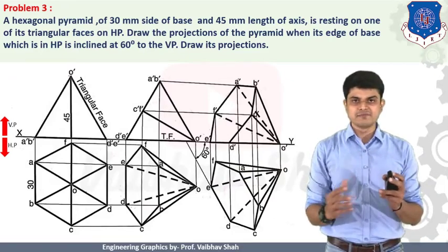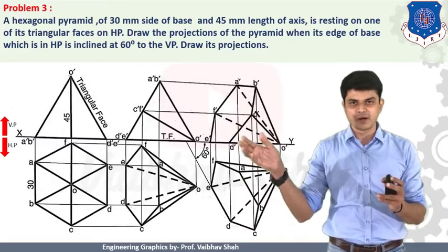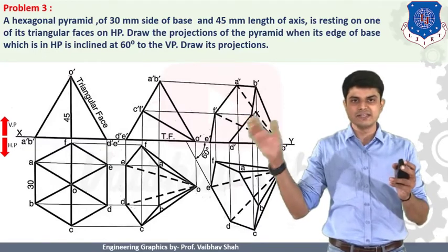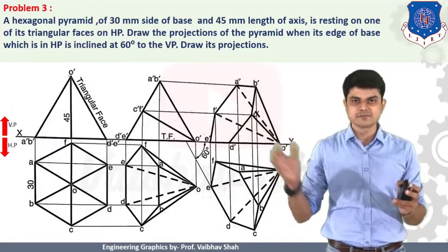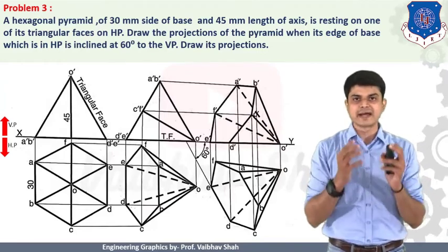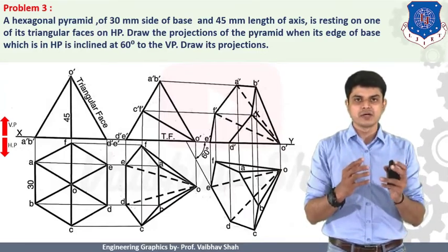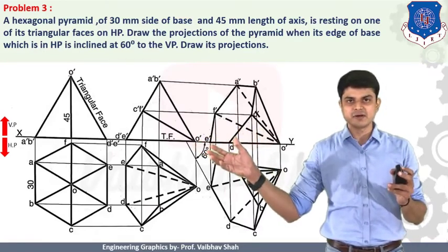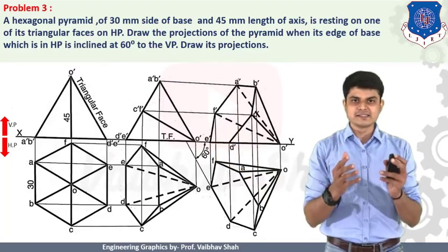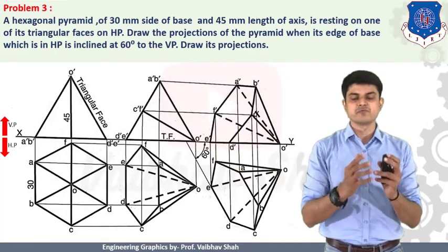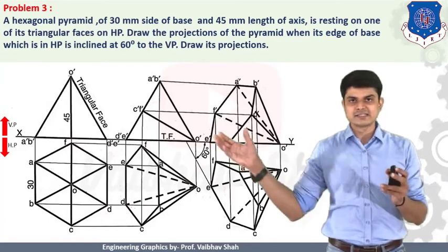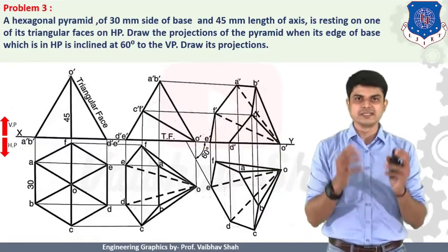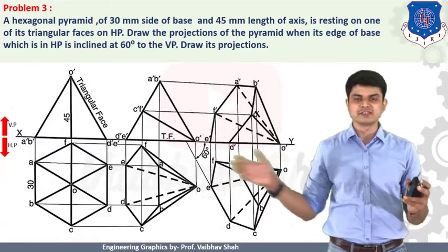So now as you can see, when we try to take the top view on the second stage, what happens is you can observe each of the points of your base like A dash, B dash, C dash, D dash, E dash, and F dash. And you can also observe this point O dash. But what you can observe is the triangular face. So the triangular face is containing what? Three sides. First O dash, D dash, O dash, E dash, and third is D dash, E dash. But as the base is completely seen, the D dash, E dash line would be a full line. But the lines O dash, D dash, and O dash, E dash, which are farthest from the observer by taking the top view, must be hidden lines as you can see in this figure.